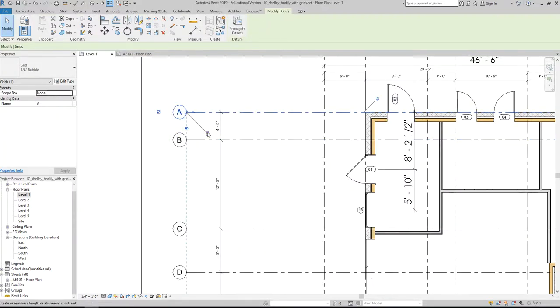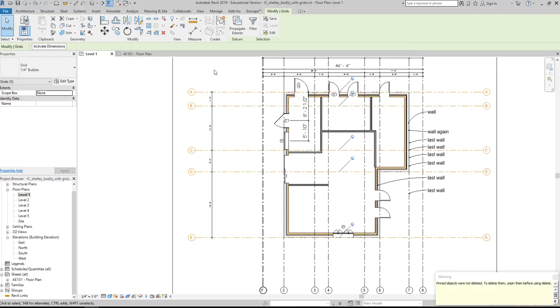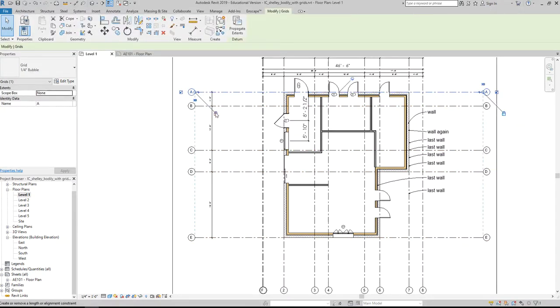These look like they're locked. And I could drag some of those in if I need to make them a little bit closer. We'll have to unlock all these. Let's grab them all at the same time and unpin them. Okay. But I can grab my, see, over-constrained. Why don't I learn my lesson, right? Do it one by one. Looks good, and they're also pinned. So these were pinned and they were locked. Sort of over-constrained it, which made it harder to move them in. Okay, but now they've all been freed up, and now I can drag them kind of nicely in.